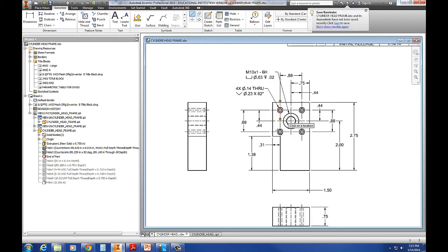Okay, so now I don't have to put 2x on those. And I don't need this one anymore, do I? Don't need that, and I don't need this because I've got that and that continuation line. Essentially, we're locating this first hole from the center of this hole, which is already located, and then locating this hole from this one. Does that make sense to you? Did one of those disappear, the first one you did? I deleted these two because I've got it over here. No, the center line that you first did, over on the right, between those two.